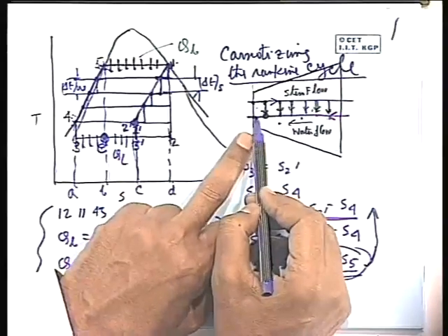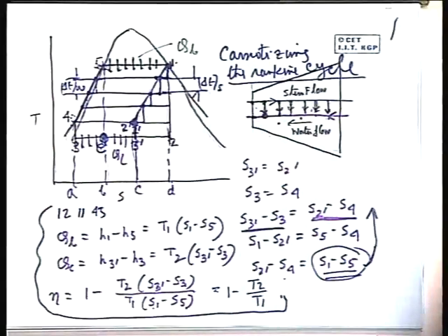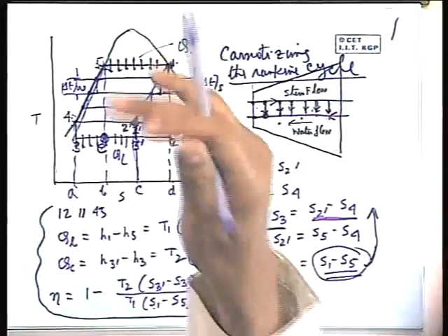At this section the temperatures are equal. If you give an infinitely long heat exchanger, you will see, if you make a counterflow heat exchanger as a simple example, hot fluid is coming in this direction, cold fluid is coming in this direction. You can never expect the outlet temperature of the cold fluid to be equal to the inlet temperature of the hot fluid. Just think with common sense. If you have to do that, you have to give an infinitely long length of the heat exchanger. You cannot exchange heat like that so that ultimately it will catch up to that temperature. That means it will be infinitely long. This type of concept cannot come in reality. This is the actual concept of reversible heat transfer, which takes infinitely large time, and automatically the equipment will be infinitely long. So, this cannot happen, number one.